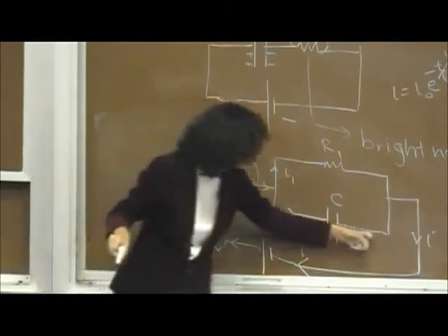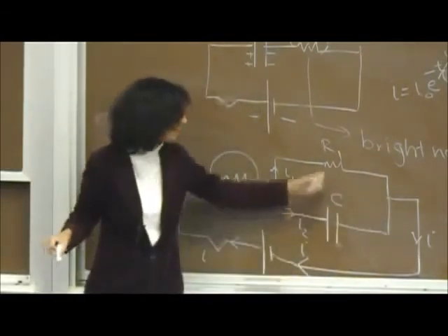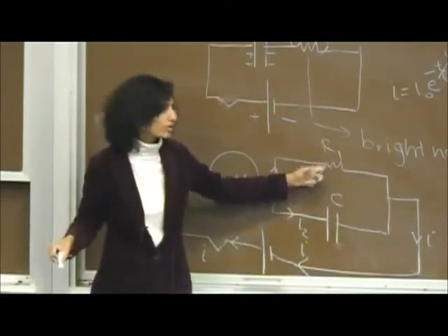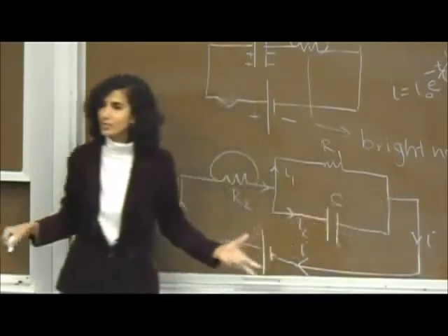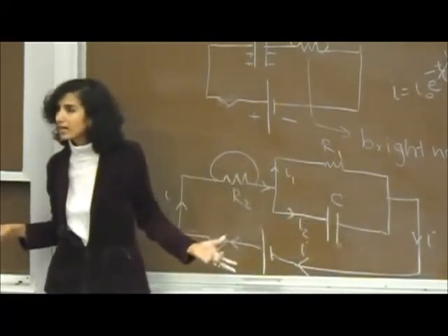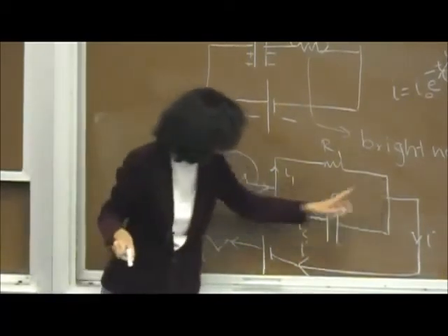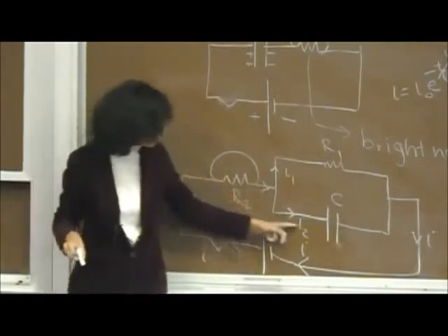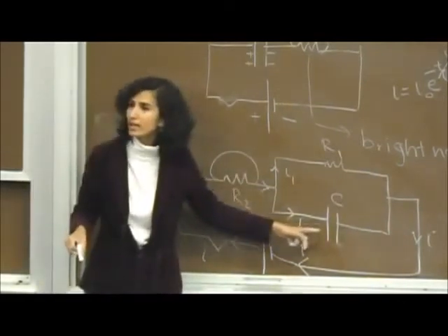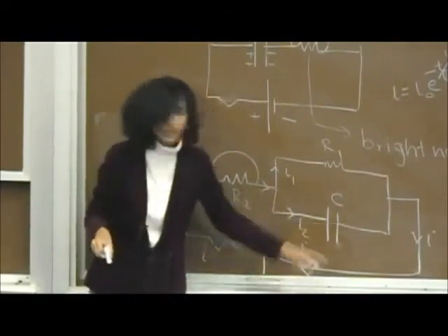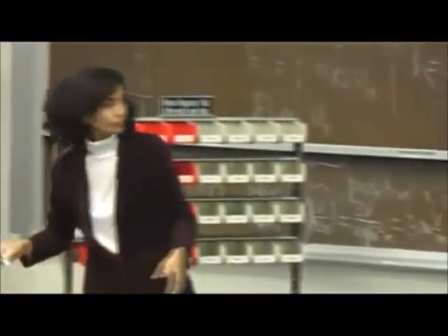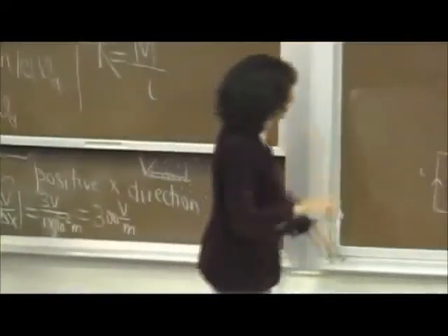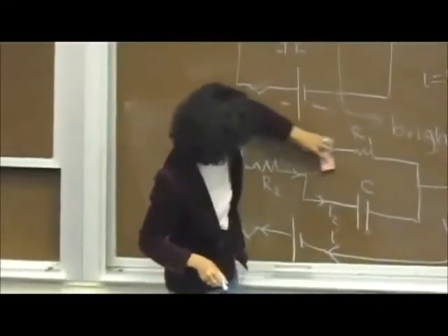Look, there is almost 0 resistance in this branch compared to this branch. Do you see that this is almost no resistance because I haven't put an explicit resistor there? So wouldn't you expect that all of the current I pretty much will be I2 initially? Almost everything will go through this, and that's why what he was saying initially is correct. And that's why initially it's as though this thing is not even there.